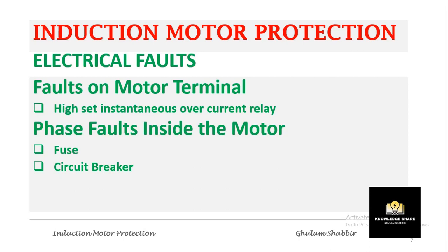Big motors, which are high voltage motors, will need to be provided with overcurrent protection. The thermal capability characteristics of the motor should be kept in mind while applying the overcurrent protection. The overcurrent relay characteristics should be below the thermal capability characteristics.